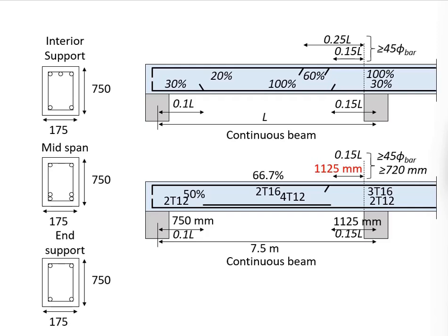And when the reinforcement bar is not properly bonded with the concrete, the performance of the reinforced concrete members will be affected. Therefore, it is normally a good practice for you to do the curtailments in order to avoid the concentration of the reinforcement bar at one place, especially at the joint.